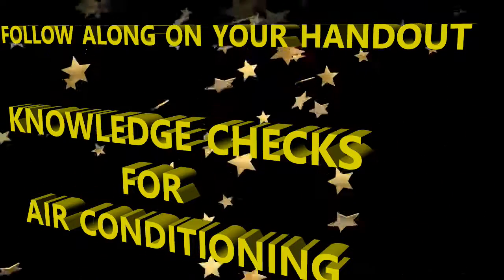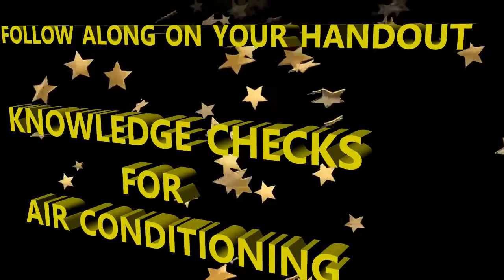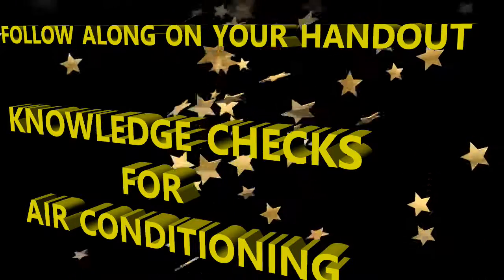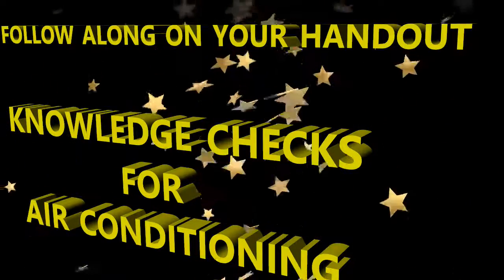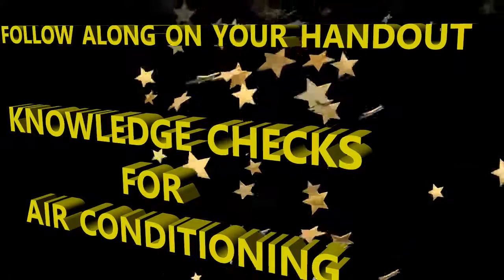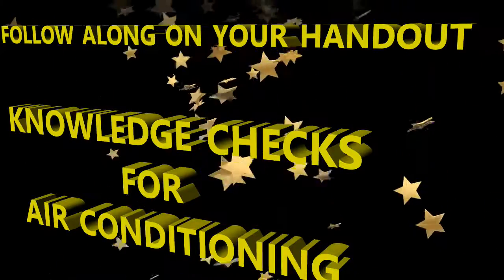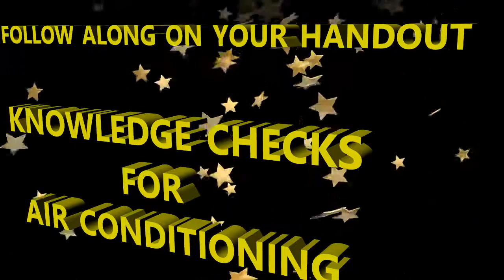So what percentage of normal flow is the low selection? There's a normal selection, there's a low and a high. Your 2 choices are 50% of normal flow or 80% of normal flow. So just know it's 80%. The low selection for the pack flow selector is 80% of normal flow. Normal flow is 100%, right? Incidentally, just so you have the knowledge, high is actually 120% of normal flow.